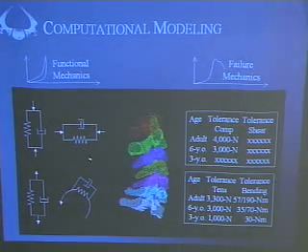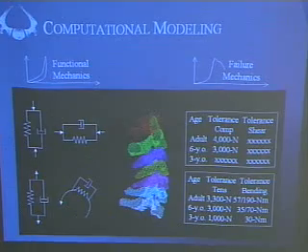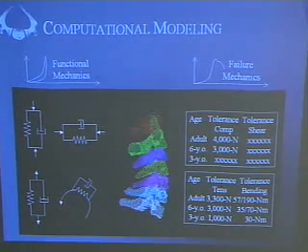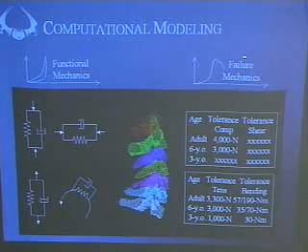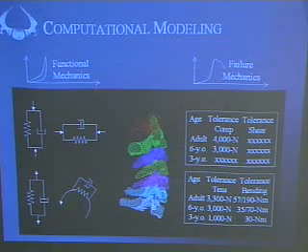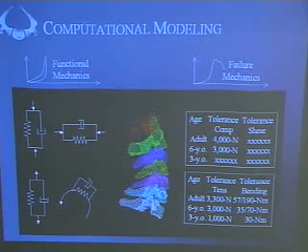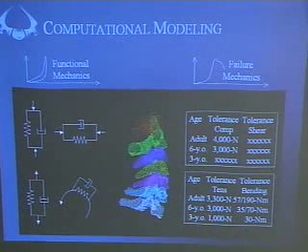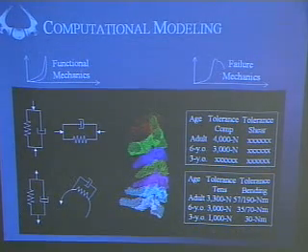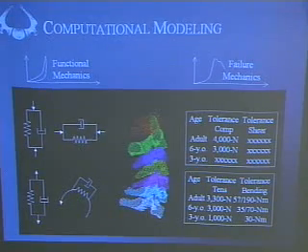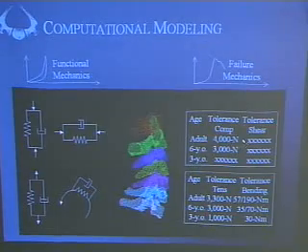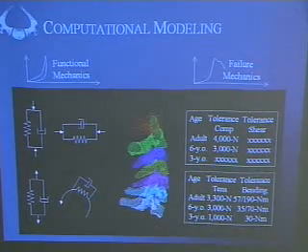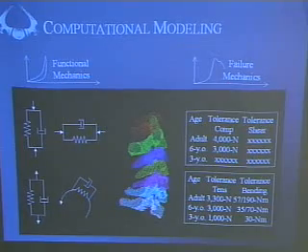As well as changing all of these parameters, we're also changing with age. So we're looking at how these different parameters develop with age, and they may not all be the same. Concerning the failure mechanics, or the tolerance criteria, I put some charts over on the right-hand side here, and these charts represent the current tolerance criteria for crash test dummy neck loads that were used as recently as 2 years ago. 2 years ago, we had very little data in terms of what we called failure in these crash test dummies.